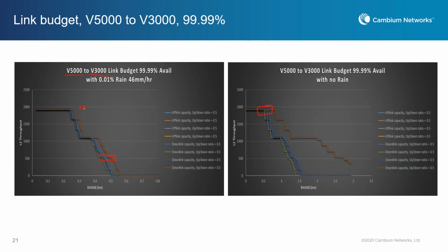When we do point-to-point long range using V3000, the distance can push further. We talk about a range of 800 meters to about 1,000 meters, depending on what throughput you want to achieve. During a normal operation day, the throughput is pretty much here.